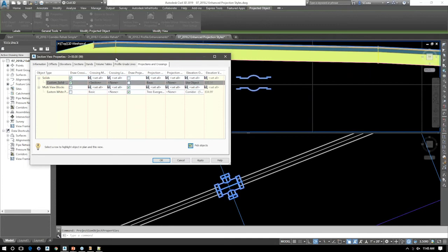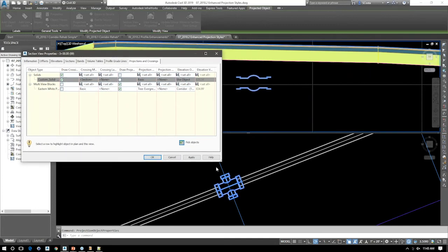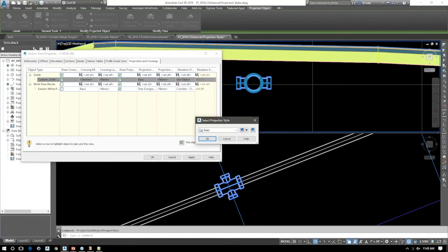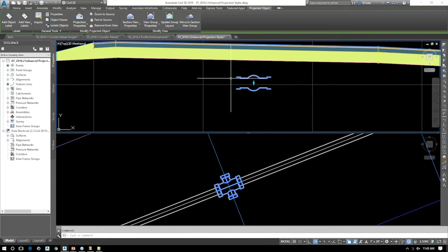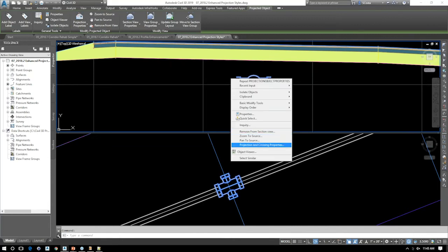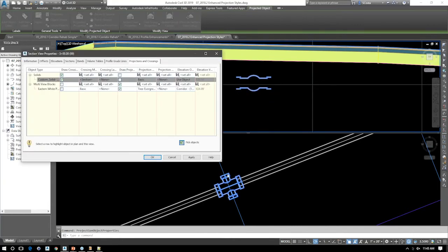What that actually does is it creates just a cross-section of the elements as they're being cut in the drawing. You can also input a projection view. If I draw the projection view, you'll see that that projection style gets thrown in. What is also useful is pointing out that if I change this back to none, the style that drives how this looks for a section and crossing is driven by the element's layer properties, not the style properties. So that was a common request.